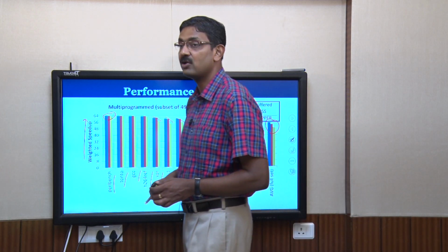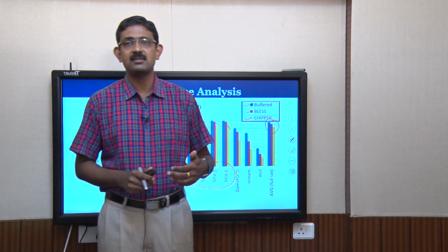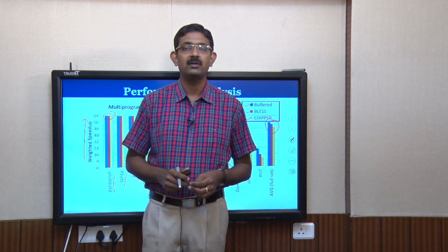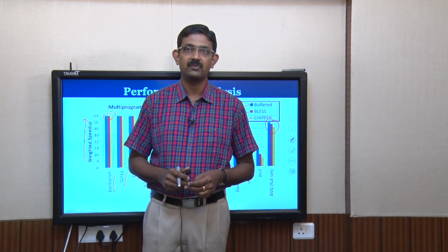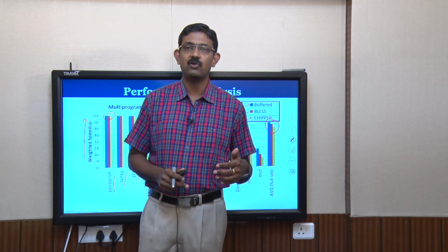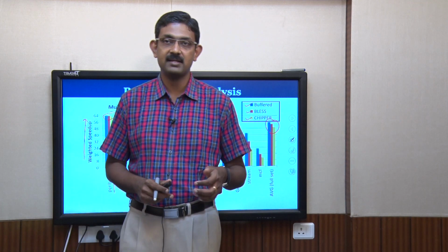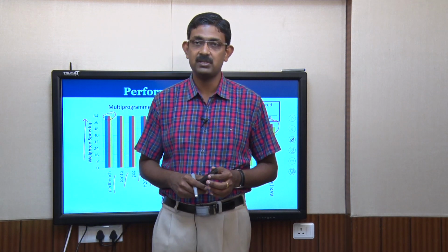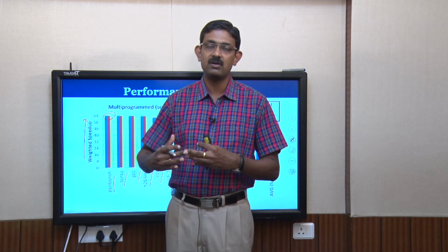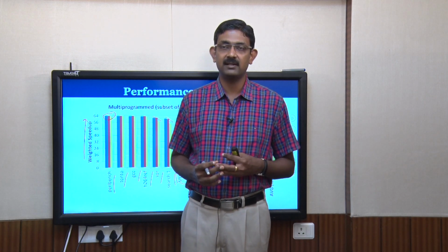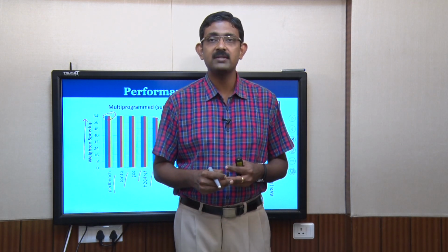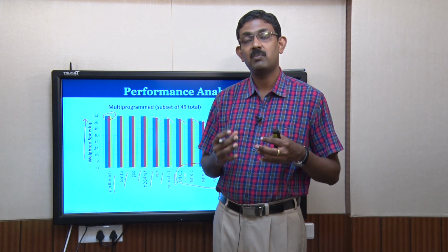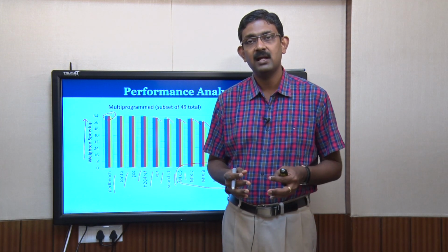So, just to summarize what we had in today's lecture, we were trying to understand that buffers, a very crucial component in giving performance to NoC routers, are really power hungry circuits. So, if we can get rid of buffers, we are going to gain a lot of power and area savings. But since buffers are an important component that governs the performance of NoC, we have to compromise on certain aspects. At very low injection rates, buffers are not going to play a significant role. So, traditional input buffered routers are going to be replaced with bufferless deflection routers, where we have pipeline latches only.